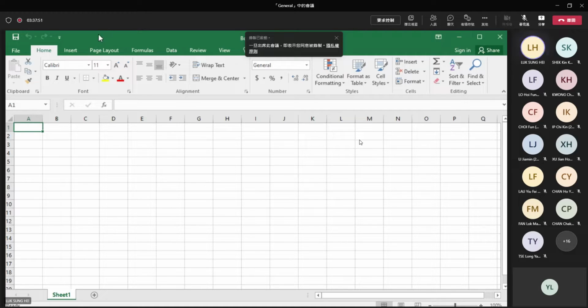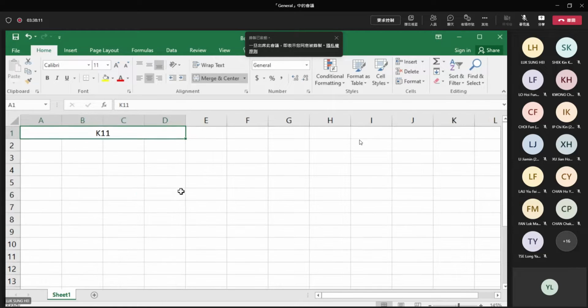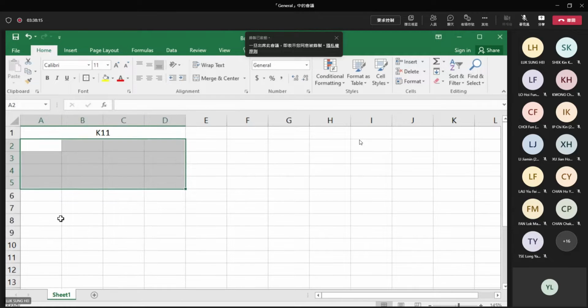In the previous example one, we constructed the structure sequence matrix together, and from the structure sequence matrix, you can identify where K11 is. Here I directly input K11 into our Excel spreadsheet. I copy it from the notes with a minus.